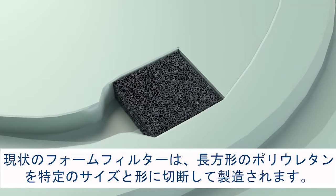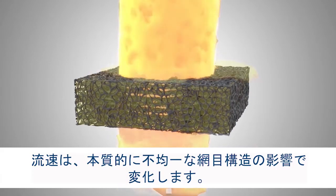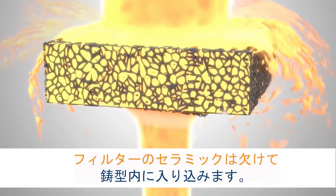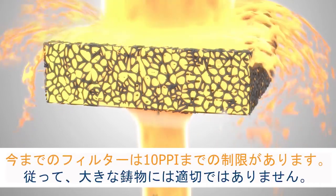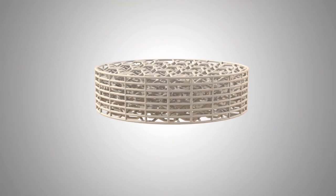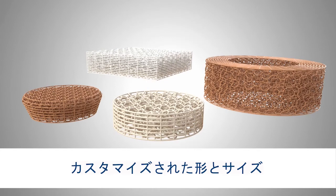When comparing foam filters to the new ASK EXACTPORE 3D filter, one can see inconsistency with the foam reticulate pore size. This can lead to variation in flow rate and capacity. Unsupported tendrils are fragile and can be damaged in shipment or mold insertion. This can allow filter bits into the casting cavity. The EXACTPORE filter was designed to fully support its filter webs with unlimited cell sizes available.